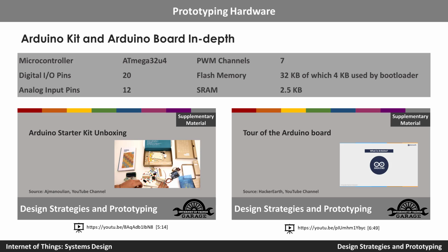Arduino is somewhat generic, general purpose, even though you can buy a microcontroller that's specialized in a particular task. Still, it is general purpose. So they are slightly bigger because they have input and output and other things that you need when you are combining different components together. But that is okay when you're prototyping, because the whole objective is to prove a point that your IoT solution works. So once you figure that out, then you need to properly manufacture them separately.